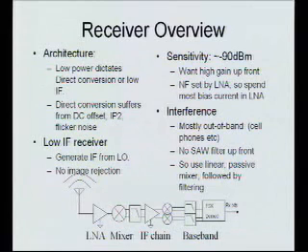You just can't do anything about that. And the question is, is image rejection worth it from a noise figure point of view? Basically what it boils down to in this case is that to do image rejection requires a certain amount of extra power. The place that power is going to come from is the LNA, because that's where all my received power is going, as I'll show. When I take that power out of the LNA, its noise figure gets worse, and it actually gets worse by more than 3 dB. So it actually costs more to do image rejection than to just dump all my power into the LNA and take the 3 dB hit.